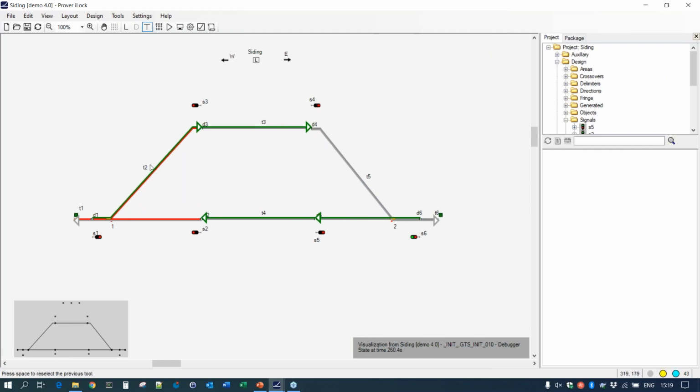Okay, if you look here at the occupation, we now pretend that the train reached this track. So I remove this. You can now see that this switch is moving. The flashing little arrow. The switch locked. Okay, sorry, I still have an occupancy here. If I remove that one, we can see that the exit route locks. And now it says green, expect green here. Okay, so let's take a train in at the station here. Occupying there, next occupying here.